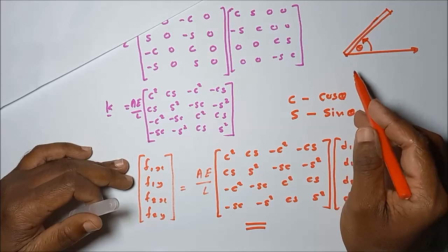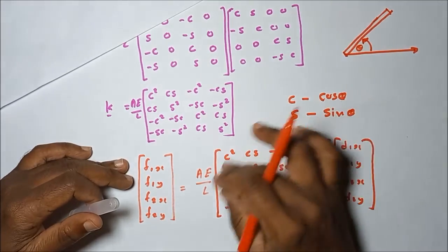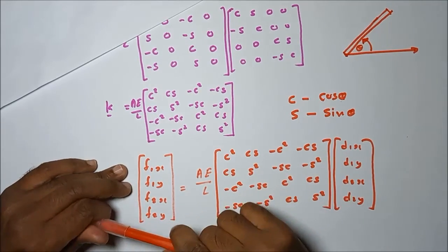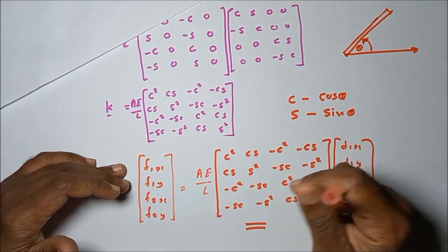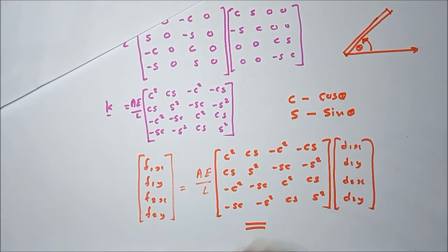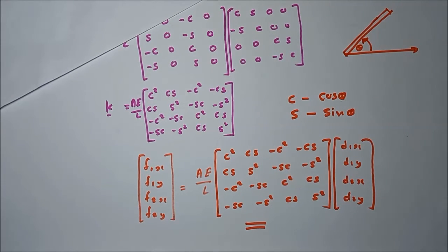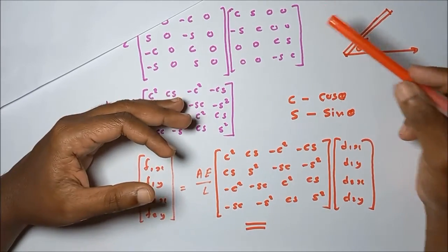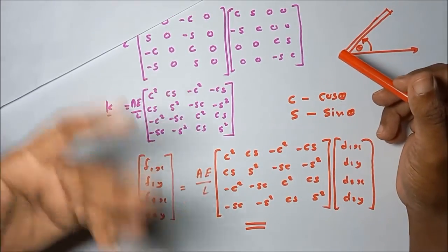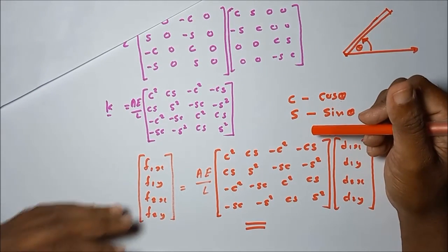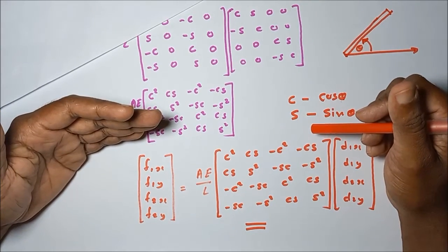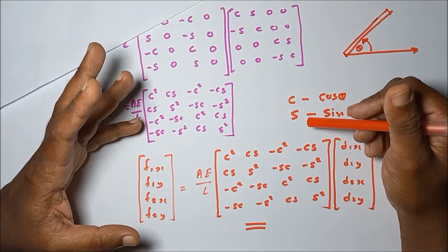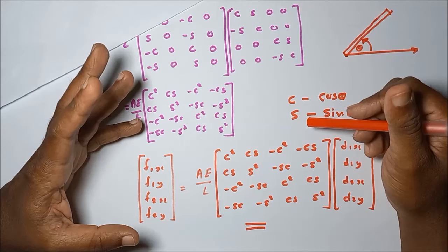For each element, by substituting the theta value into this equation, we can obtain the element stiffness matrices, then assemble all of these equations. After obtaining the global equation, by substituting the boundary conditions, the known displacements and known forces, we can find the unknowns. This is how we solve this kind of two-dimensional truss problem using the finite element analysis method.